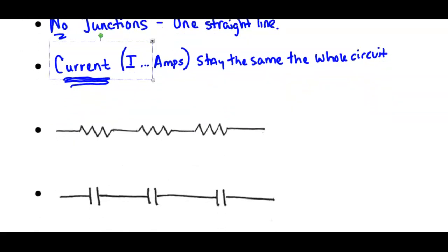So I have here a resistor set drawn in series. So I have resistor 1. Whoops, that didn't draw. Try that again. I have resistor 1, I have resistor 2, and I have resistor 3. Now if I wanted to find out what the total resistance is across these, or the equivalent resistance, I can simply add them up.